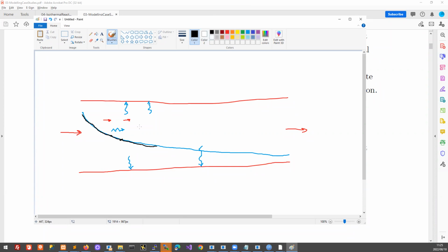And another thing to think about is that, well, the reaction is only happening at the surface here. It's not happening at the interior points of the fluid. So it's not completely clear to us as yet how we are going to account for that, right? We'd like to write a nice balance here, and it seems natural to us. We know A is reacting, we would include a reaction term also, but we can see we can't really do that, because if we are writing a balance on this little box here, where the reaction is not happening, it's not legal, if you like. It's not valid to write a reaction term here also.